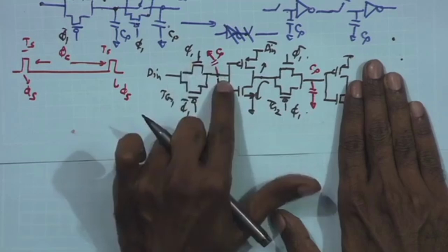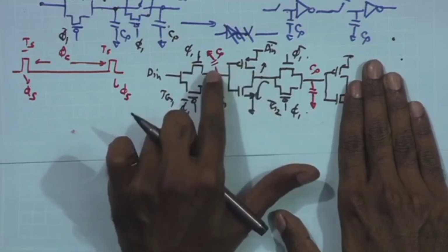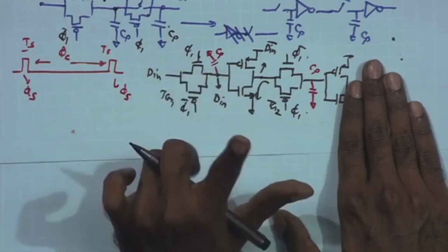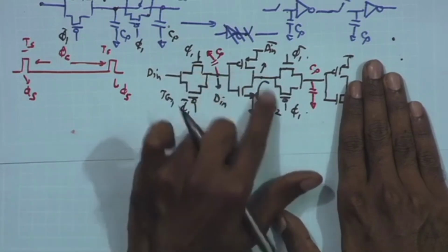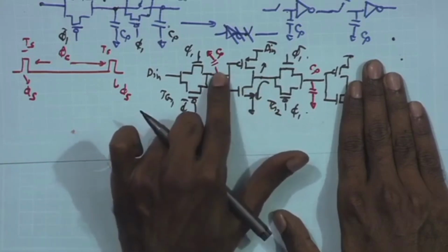When it is getting written, or when this latch is on, we do not need feedback, because at that point I need this node value to be determined by the input value. But when this is getting off, then I need the feedback to be woken up and retain this data.